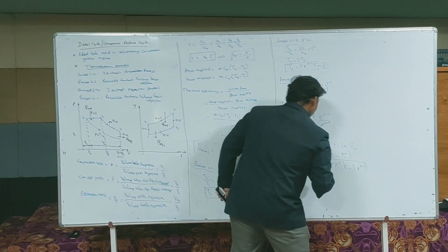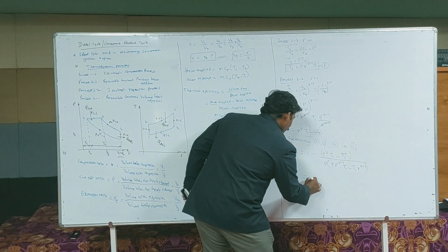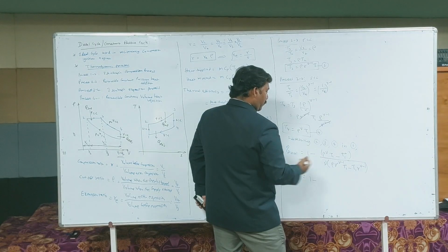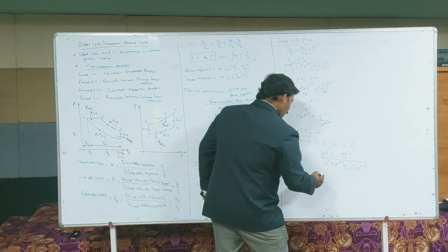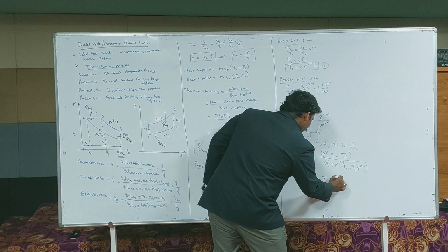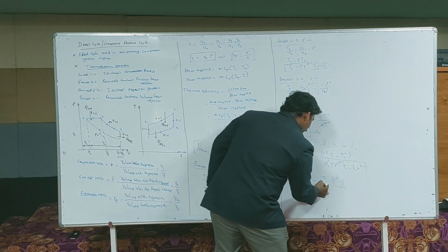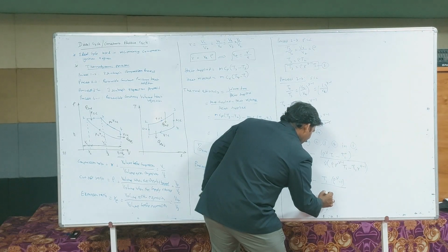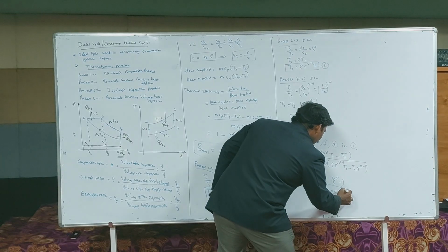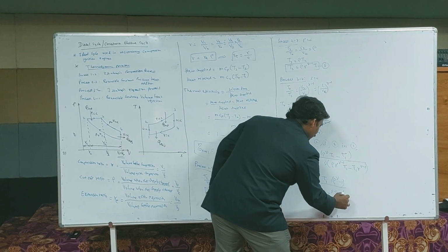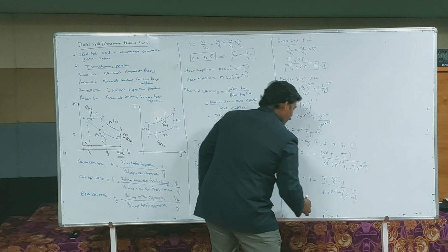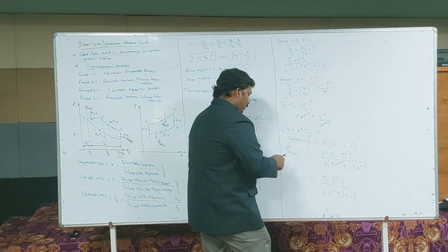So after this, if you rearrange, you will get 1 minus, you take T1 common term, R power gamma minus 1 common term, both. So in numerator only T1 common term, so T1 into rho power gamma minus 1. In denominator you take gamma, R power gamma minus 1 is already available, and T1 you take common term. So the remaining is only rho here and here 1. Okay. So in this one the T1 got cancelled.